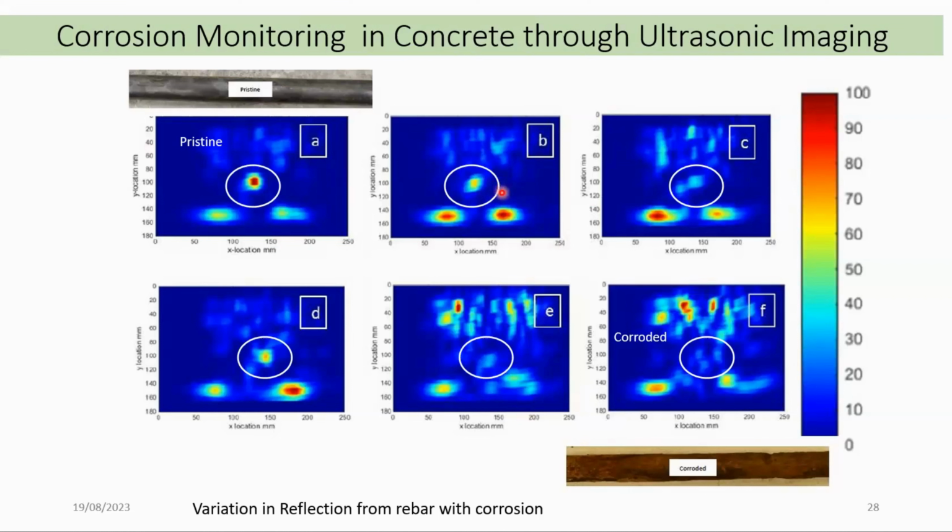The reason is, if you look at this analogy, if you're able to see my pen, say this is a steel bar and this is concrete around it. How does corrosion happen? Initially a soft layer of rust forms around the steel bar, and this soft layer pushes the concrete. Unless this push is strong enough to cause cracks, there won't be any surface cracks showing. So if you use drones, you will only be able to pick up defects at a very advanced stage when the cracks have shown up.